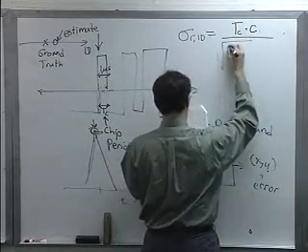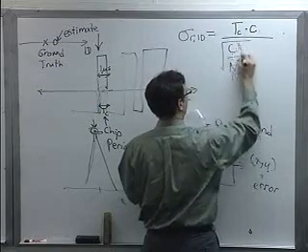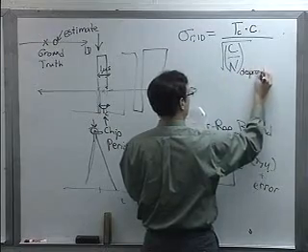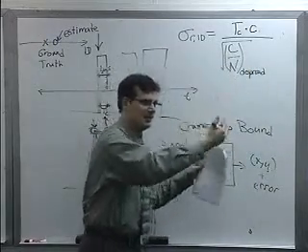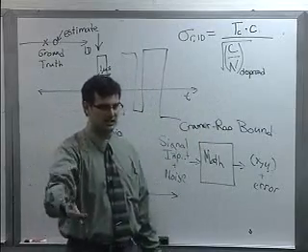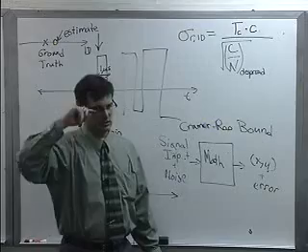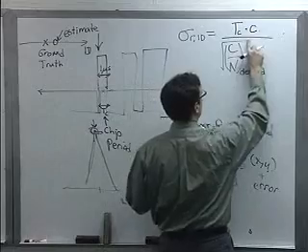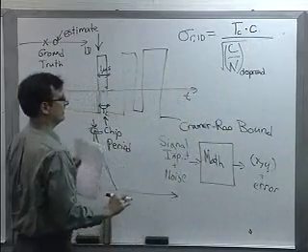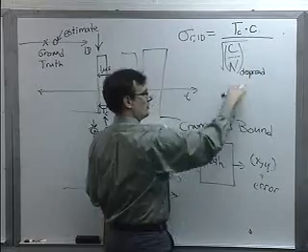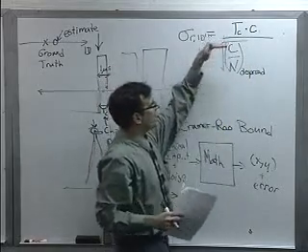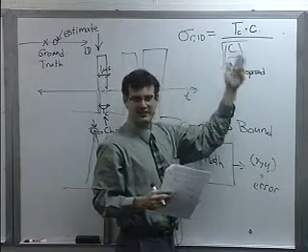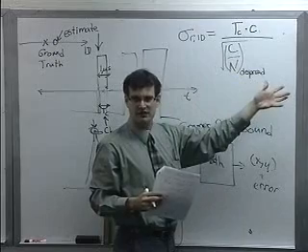Square root of C over N despread. So we take our raw C over N that's coming into our receiver, and then we add our processing gain, which is going to be 40 dB in a GPS receiver. And that's our baseline formula. So if we have a good despread carrier to noise ratio, say 20 dB, we'll get 1,000 feet up here divided by square root of 100 down here. So then we'll get down to about 100 feet, 30 meters.